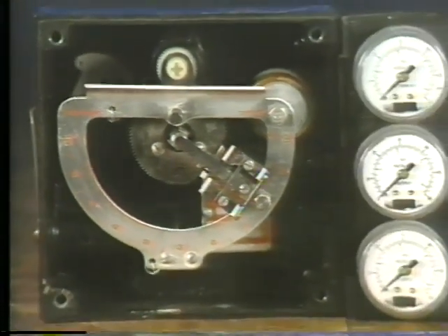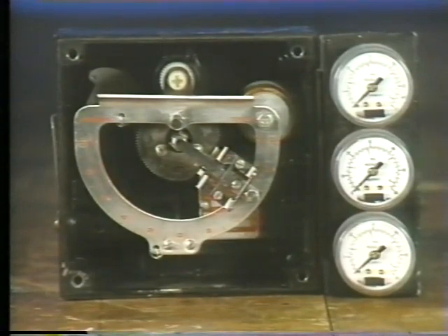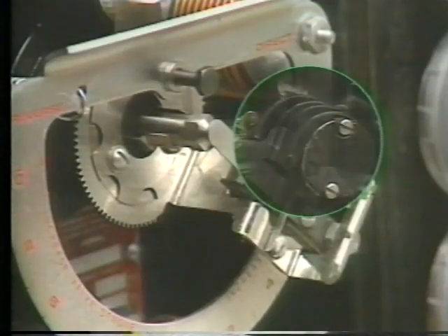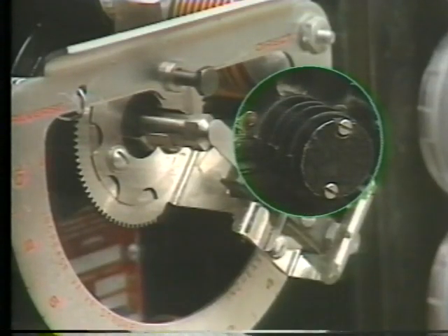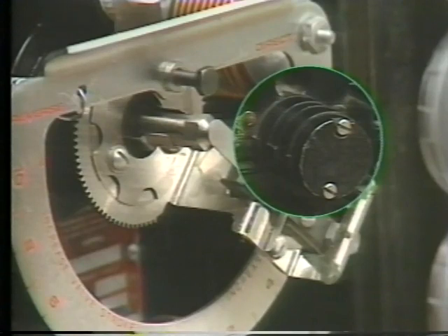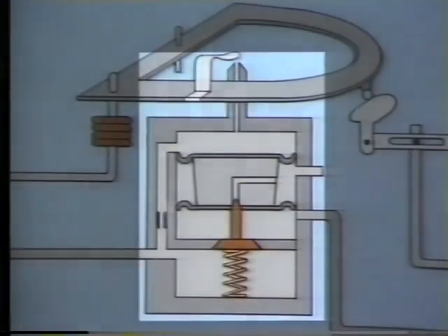There's another unique aspect about this flapper nozzle arrangement, and that is that it's combined with a pilot valve type of mechanism. It's this flapper nozzle pilot valve combination, or relay, that directs air pressure to an actuator. We'll use a simplified illustration to see how. This illustration shows some of the inside parts of the relay. Let's identify some of these parts and then see how they work to regulate airflow to the actuator.